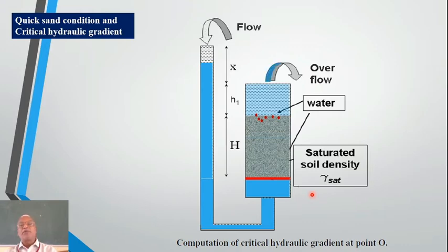Increase it a little more, what happens is there will be water which is flowing out, because there is an effective head which is above this, right? Above this much, whatever head is there, with that head the water starts flowing out. Then still further if you increase, what happens is there may be a condition where the particles of soil will be lifted up and drop down. You can just see here the pressure, effective pressure is so much that particles themselves will be lifted up and then again pulled back.